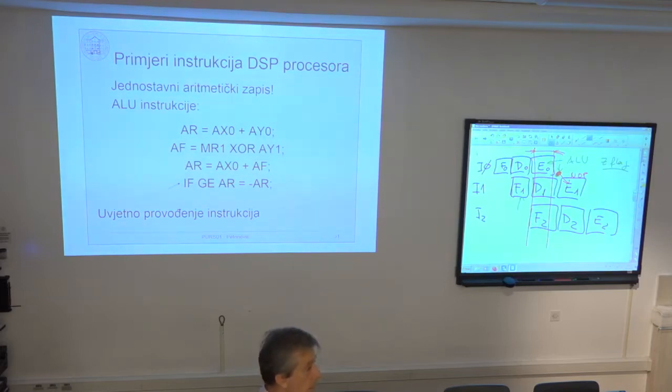And this kind of architecture is called visible pipeline. So they call it, the pipeline is an exposed pipeline. And for the case when you have the hardware that takes care of the pipeline, it is an invisible pipeline. Because for the programmer, it doesn't matter how he combines instructions. The hardware will take care that the next instruction takes the proper argument of the previous instruction. But with this exposed pipeline, they say it's not something that we can implement in hardware. It's too complicated. Let's put it in the preprocessor phase.